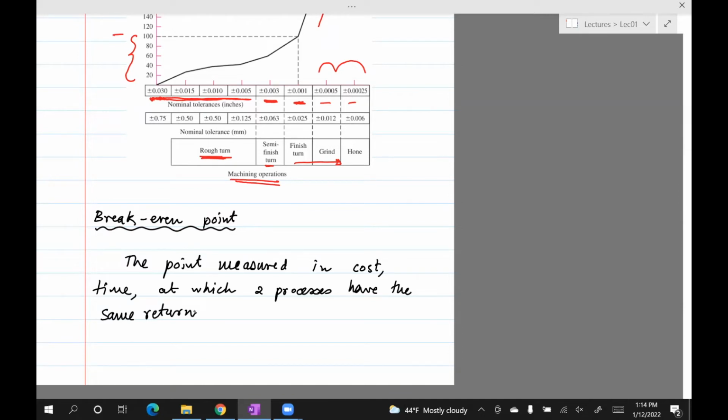So there's more cost to buy it compared to a lathe. So after you reach a certain production level, maybe 5,000 or 20,000 units, you will achieve a point where CNC outperforms a lathe in terms of profits. If your production is more than that break-even point, then you probably want to invest in a CNC and not into a lathe.